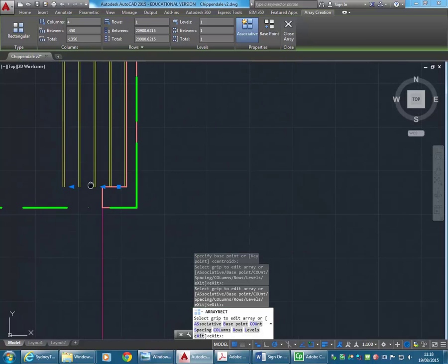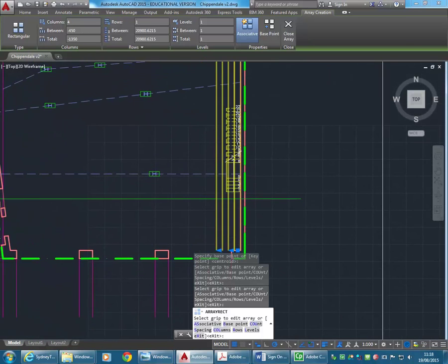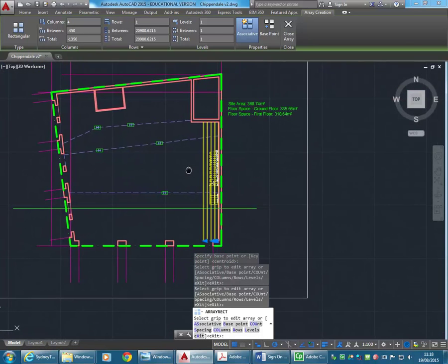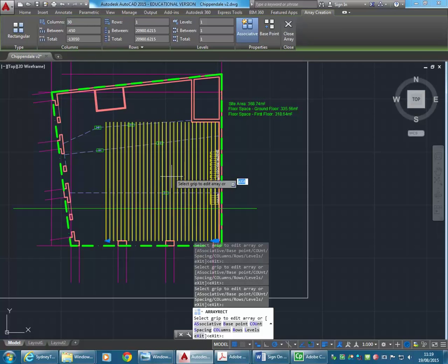And then the total, so this is where the array is much improved in AutoCAD because it is parametric. So you can come back and adjust the properties afterwards. Here I'm just taking a stab at the column total. So I'll say 30 at a guess. But that's not enough. So I can come back and say instead 40.